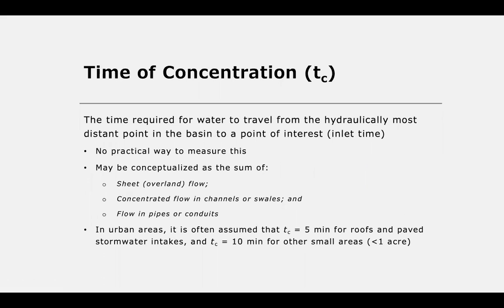So how do we determine an appropriate duration to use in this equation? One way we can do this is by determining the time of concentration. This is the time required for water to travel from the hydraulically most distant point in the basin to a point of interest, such as an inlet, and it's sometimes referred to as the inlet time. There's really no practical way of measuring this.